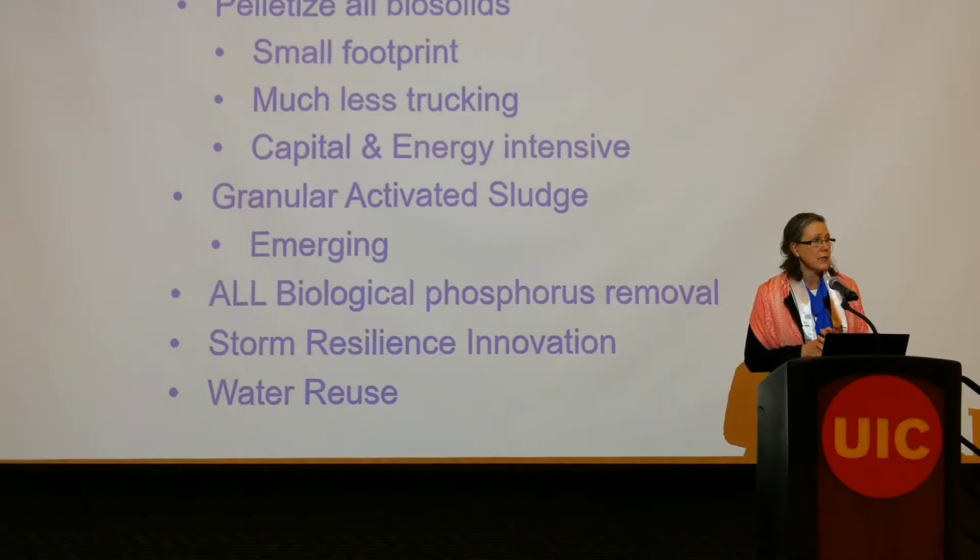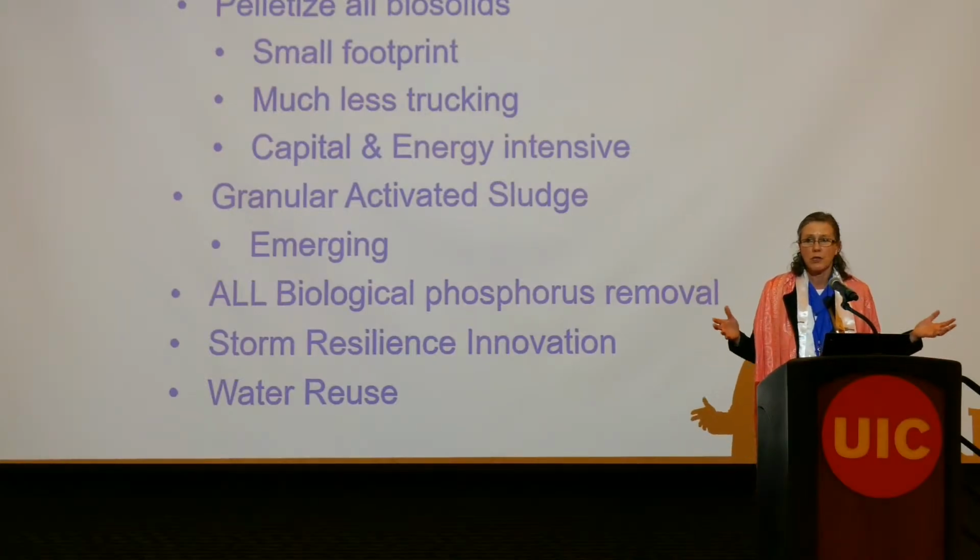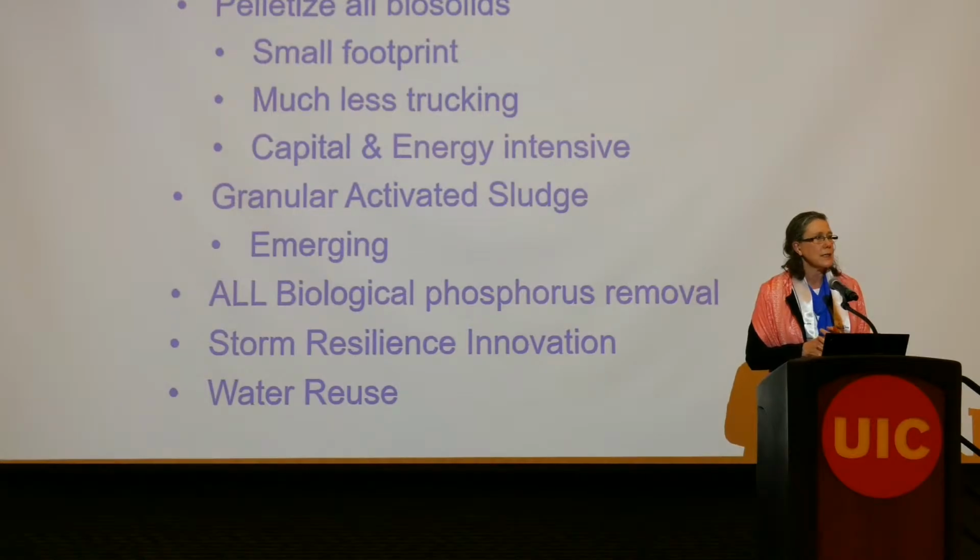In El Paso, Texas, this year was brought online the largest direct potable reuse system in the United States of America at 10 MGD. That is wastewater going to advanced treatment, going to a permitted drinking water treatment facility with no environmental buffer such as a lake or river in between. Then also, and my favorite, is Windhoek in Namibia, in Africa, which has been doing reuse water since 1968, which is the year of my birth. So we share this birthday, and that reuse system cannot fail because all that water is required for basic sanitation